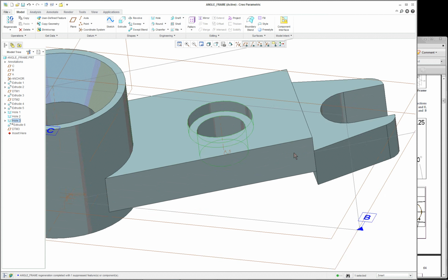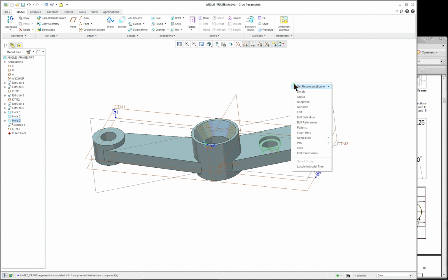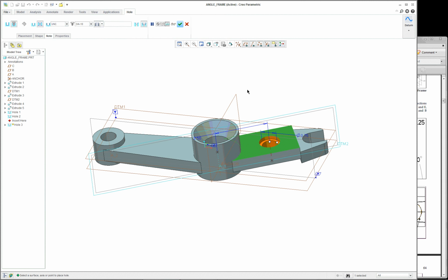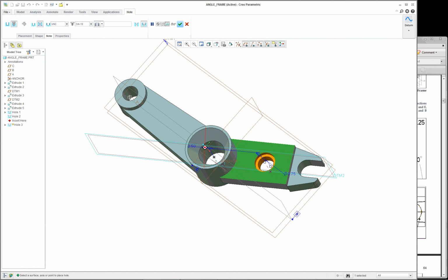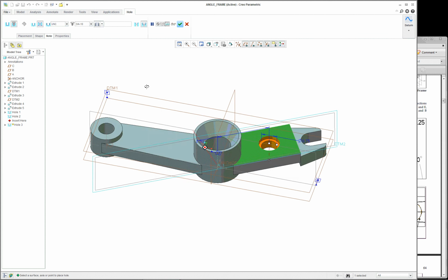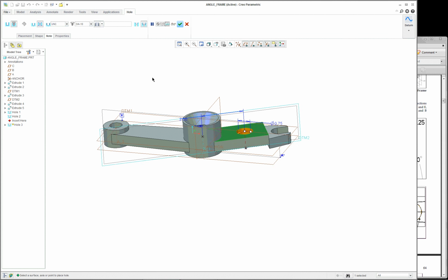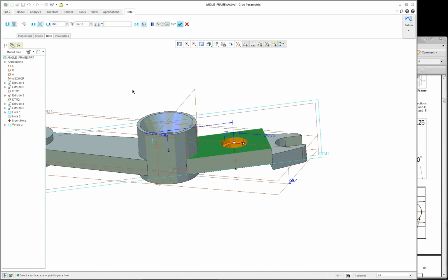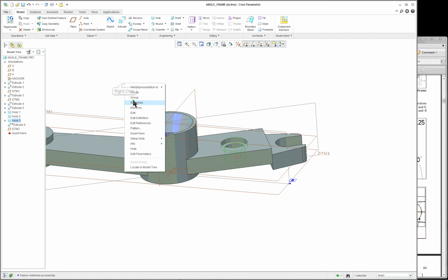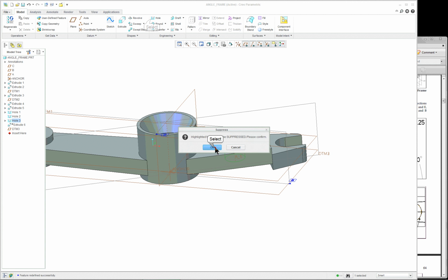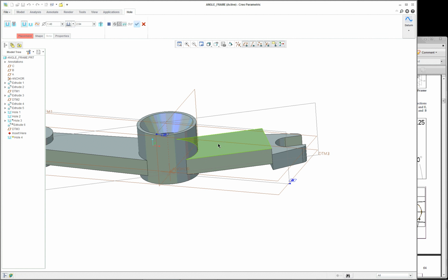The counterbore hole, a little bit, maybe not hard, but a little bit different. You want to make sure when you place this that you set up the dimensioning scheme or references correctly. And take a look at this. So in this case here, why don't we suppress it and put in our own hole. So this is going to be a standard hole, no thread, clearance.